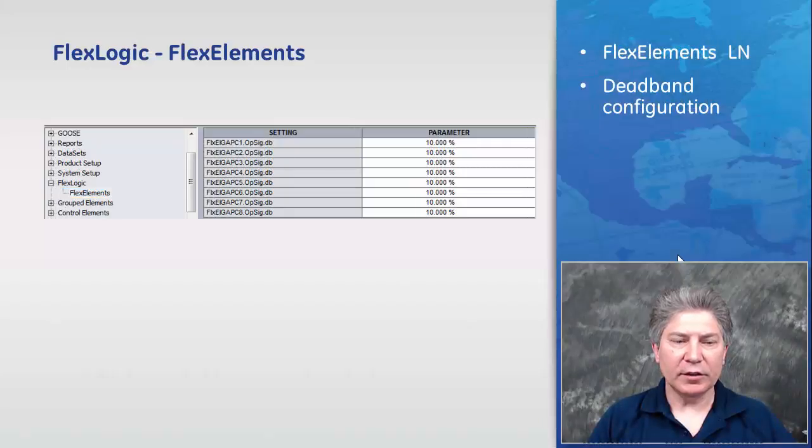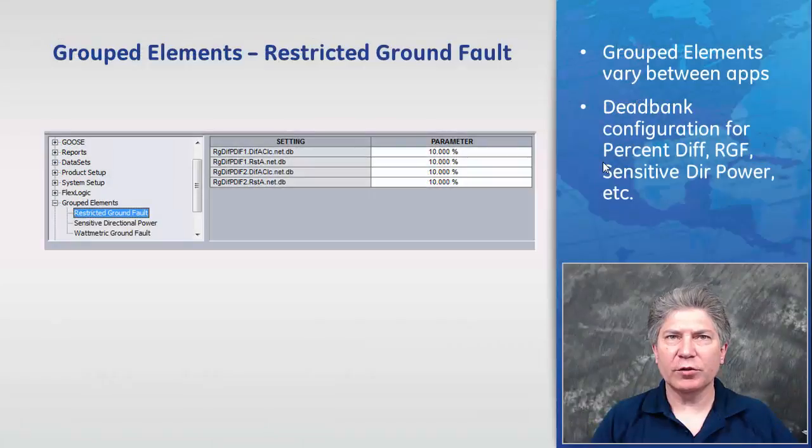Next, we'll take a look at the flex logic. Under flex logic, we have flex elements. The flex elements now have their own logical node. And here we can set up the deadband for the flex element operand for Goose and reports. Grouped elements vary between the different application types.